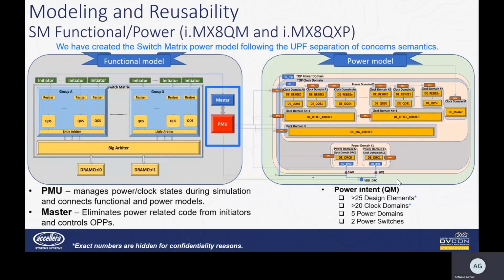So yes, we have described the power intent and management for the IMX8 QuadMax using the previously presented power clock arc methodology. It contains about 1 voltage domain with low power support, about 5 power domains, and more than 25 clock domains with enabled hardware automatic clock gating mechanism.